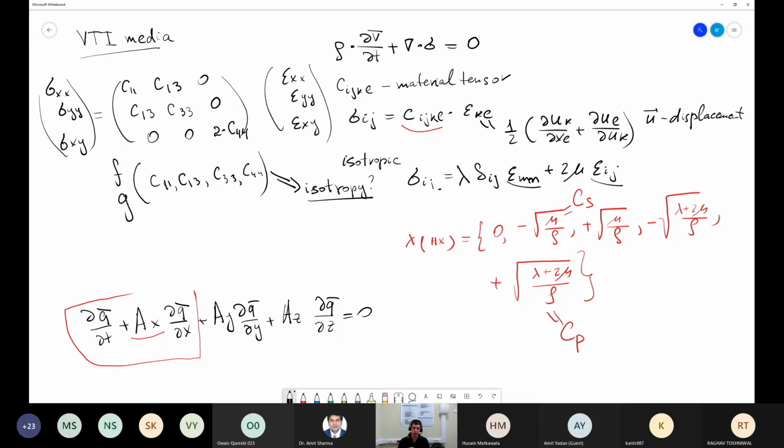In this case, we will obtain 3 different eigenvalues by modulus, so 3 different waves propagate inside the porous medium: the wave inside the fluid, the wave inside the skeleton, and another wave due to the interchange of the pulse between the acoustic fluid in the pores and the elastic skeleton in this medium.